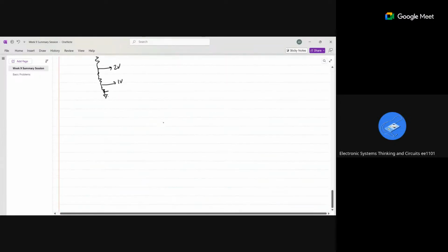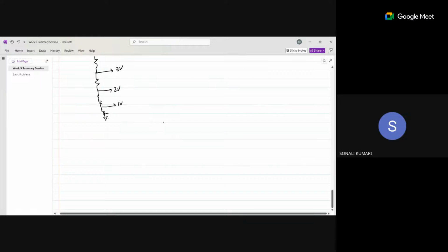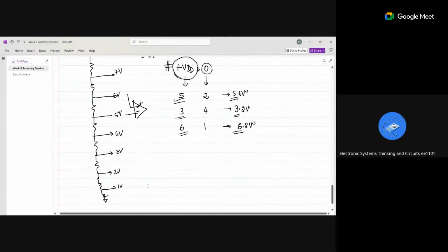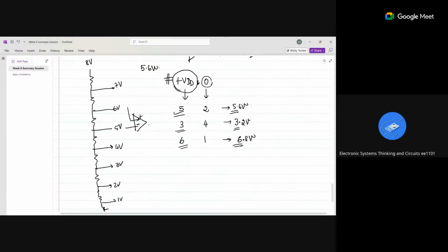So basically, flash ADC is the simplest ADC. Normally nowadays flash ADCs are not very common because, let me take this one, here there are only 8 levels, right? For 8 levels, I need 1, 2, 3, 4, 5, 6, 7, 8 resistors and around 8 to 9 amplifiers also, right?